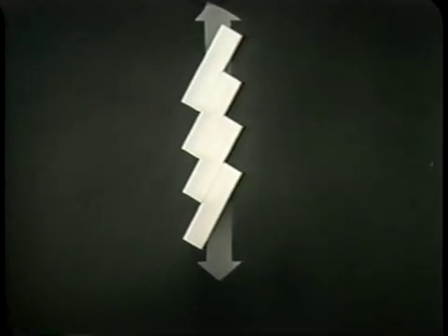In sliding over each other in plastic deformation, the crystal blocks rotate, causing the crystal to become elongated. In tension, the crystal is stretched parallel to the axis of tension. In compression, the crystal is stretched perpendicular to the axis of compression. It is by this process that the metal grains become elongated and uniformly oriented when an alloy is cold worked.